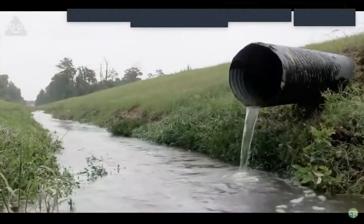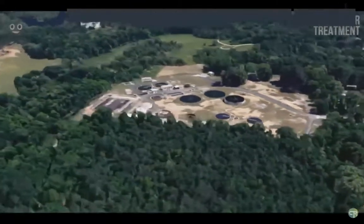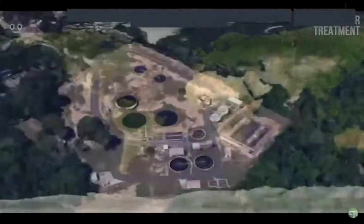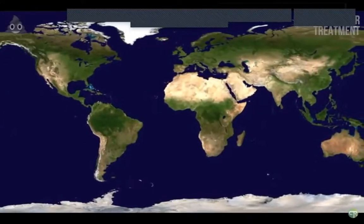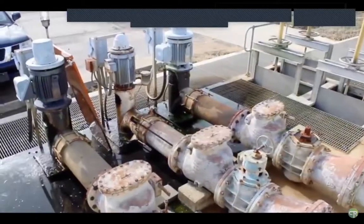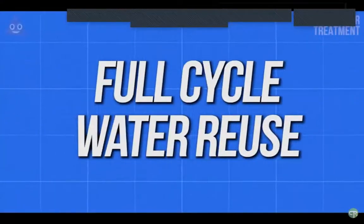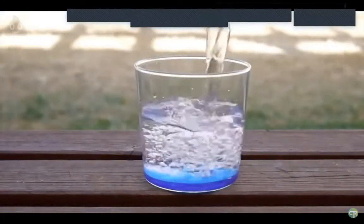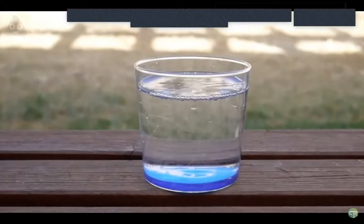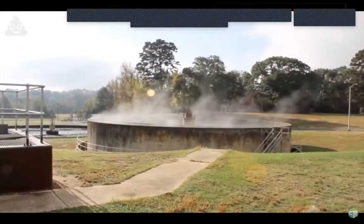Effluent release exists in one of two forms. In most cases, the now treated water is released back into a stream or lake or other water source. In rare cases, usually in areas where water is scarce, the effluent discharge from a wastewater treatment plant can be discharged into another treatment plant directly where it will be treated further for consumption. This is referred to as full-cycle water reuse. From a chemical perspective, the final drinking water is the same as normal treated water that flows through your pipes now, but due to the connotation of your drinking water being sewage just days before, this treatment process is normally shied away from or not heavily publicized.